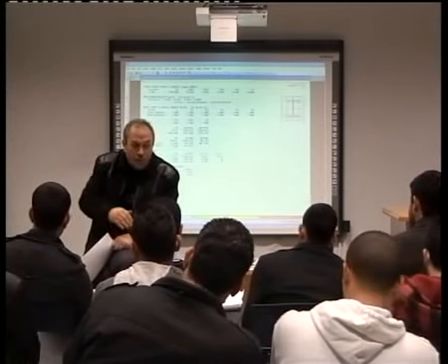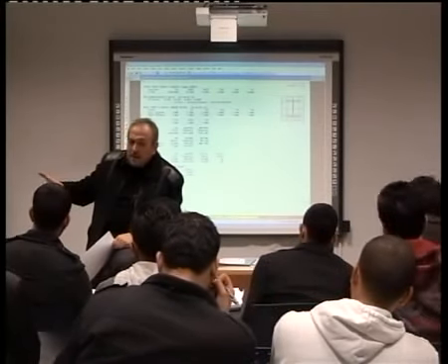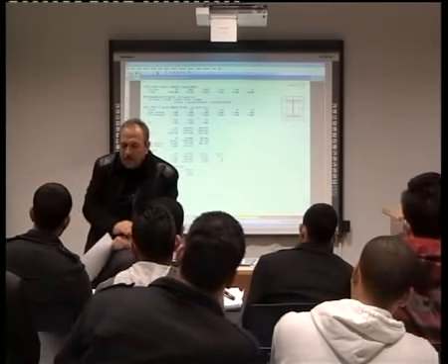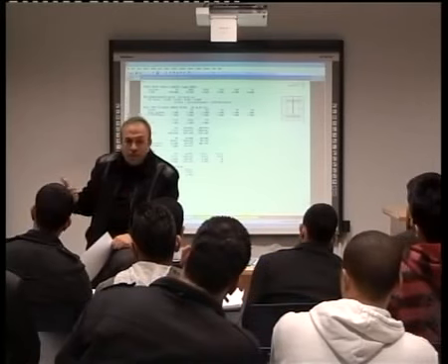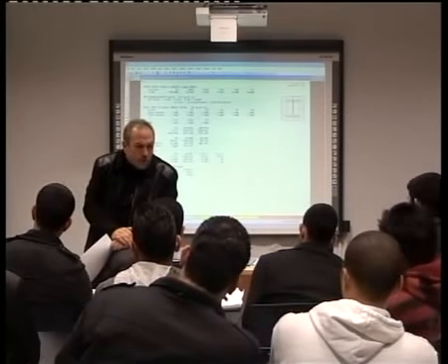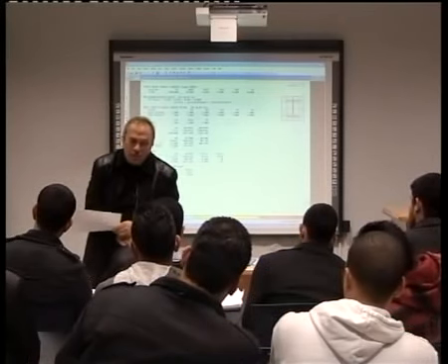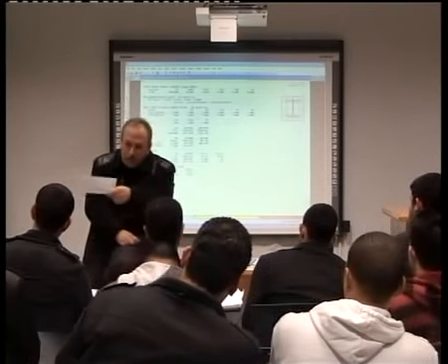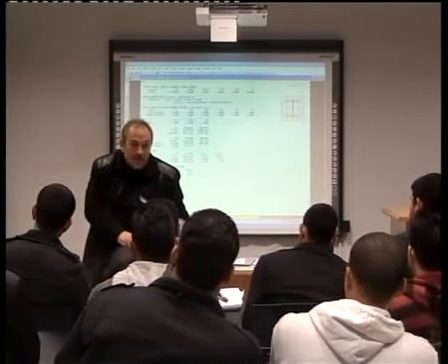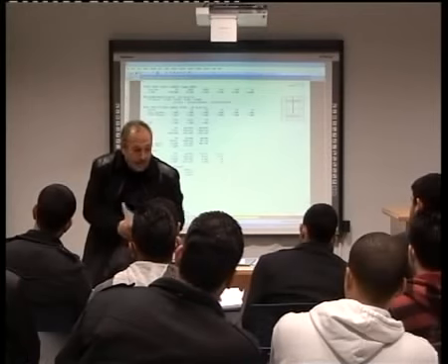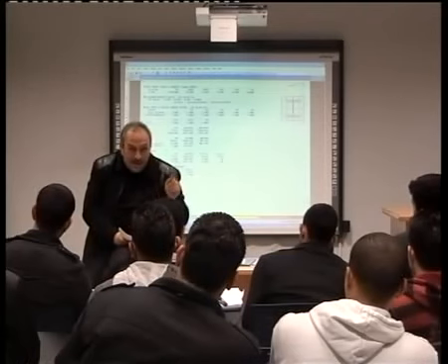When you do the design many times, I tell you that this column is IBE 200. You tell me no, it's not. It will never be like this, because by your sense, you know that this column should be IBE 400. In reinforced concrete, we did many designs. If I tell you that the slab is 12 centimeter thick, you will say come on, it's never 12 centimeter thick for such a span. So this feeling comes to support both eyes. It does not substitute any of them, but it is a support of both eyes.